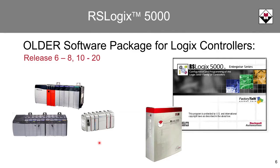RSLogix 5000 supports older CompactLogix and ControlLogix controllers. CompactLogix part numbers start with 1768 and 1769, and ControlLogix part numbers start with 1756. You do have to verify which software version your particular controller will support. You can go to the Rockwell Automation Product Compatibility and Download Center website, or PCDC for short, to determine version compatibility. When you type in the part number of the controller you have, it will show you what versions are supported by that controller. This software package only goes up to version 20.